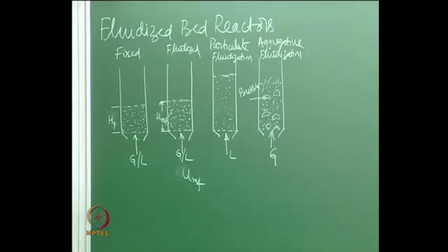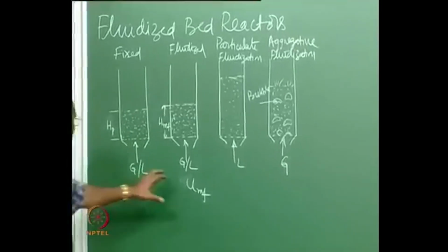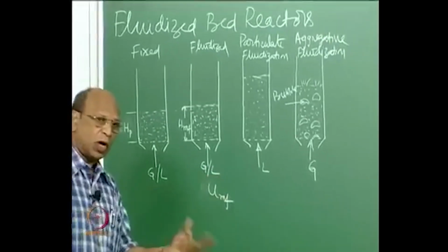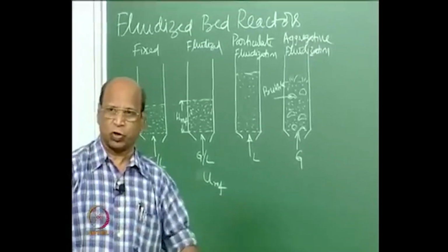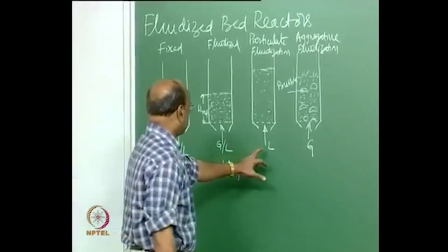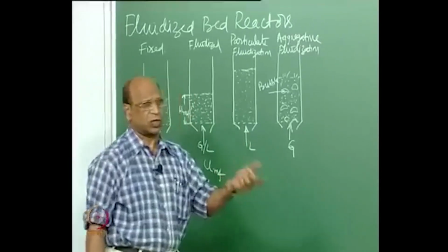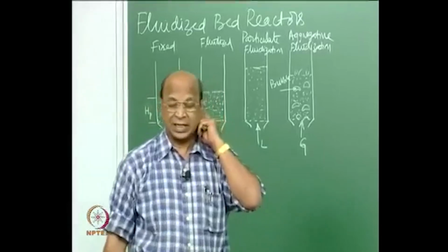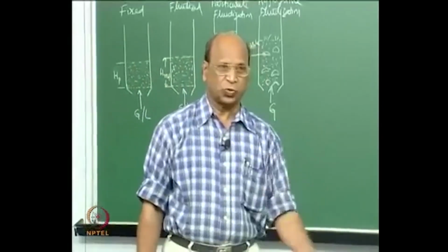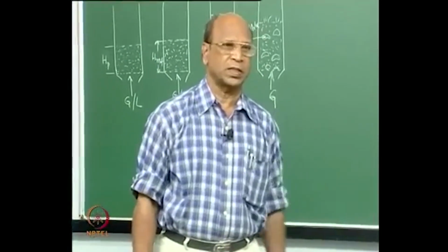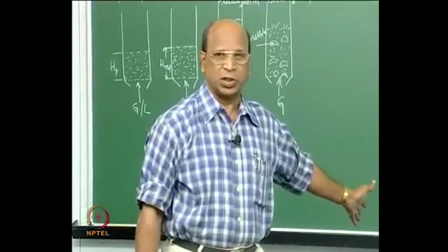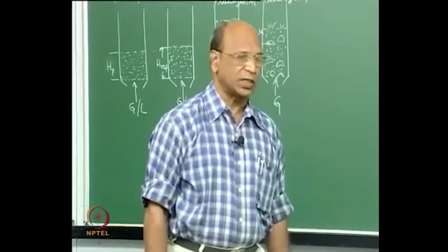So, essentially what we have to remember here is that till minimum fluidization velocity, whether you have gas or liquid does not matter, because both are going to behave the same way. Beyond that, there is liquid fluidization, liquid solid, where liquid solid applications in biochemical engineering are many. For example, wastewater is one of the applications, liquid solid systems using fluidized beds.